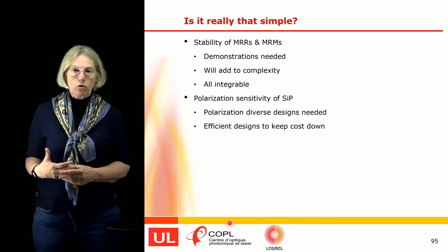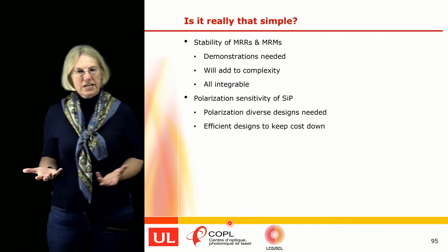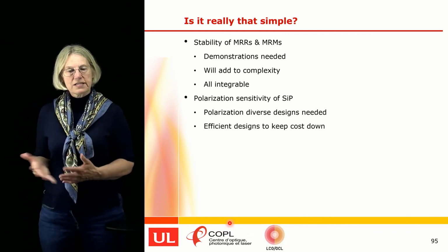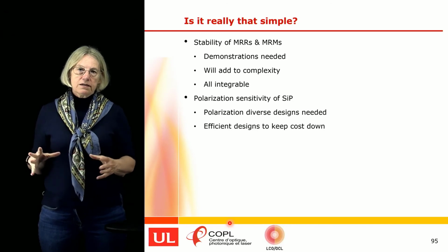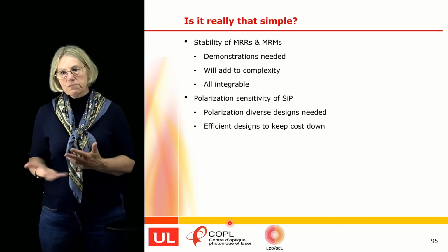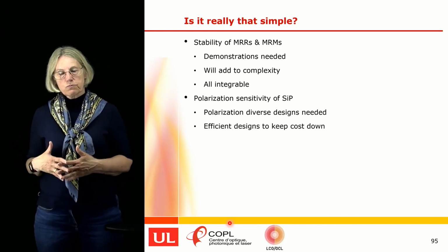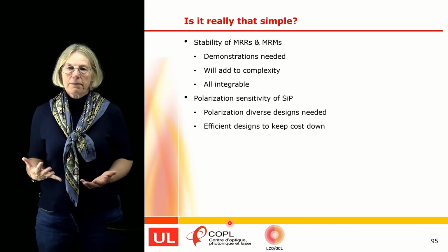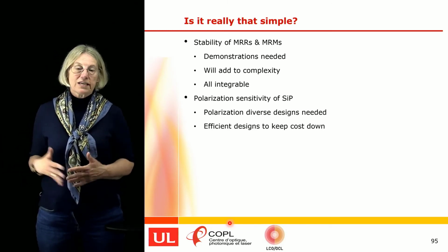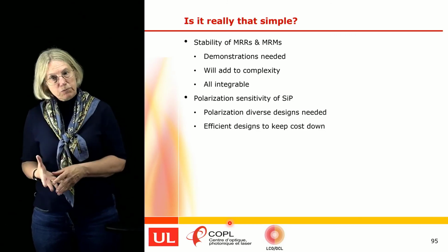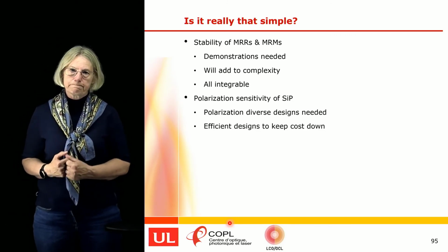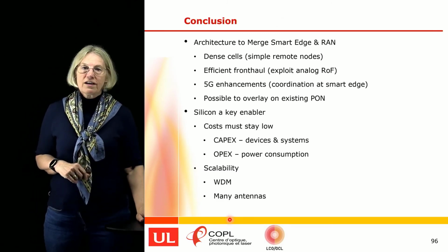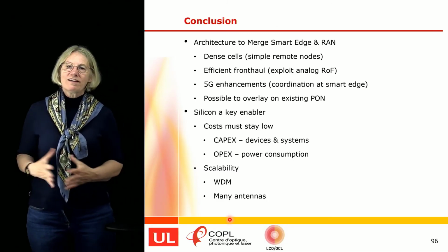Another challenging aspect in working with silicon photonics is the polarization sensitivity of silicon. It only supports one polarization. So we need polarization diverse designs. There are several that have been demonstrated. I mentioned the one from Fabulous earlier. But of course, it's easy to do some designs which just multiply the number of components. But we'd like to do something a little more clever that keeps it very efficient, keeps the footprint small. Of course, if the footprint's small, the power consumption is low also. Very, very important.